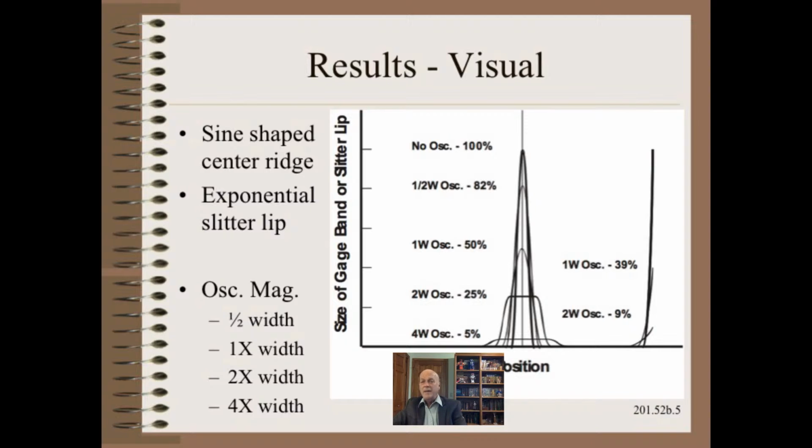However, this magnitude of oscillation may be economically viable only for narrower defects, with the exception of blown film die or tower oscillation that is not limited in that way. This is also in line with field practice, where oscillation is used primarily for narrower defects such as corrugations and narrow ridges.